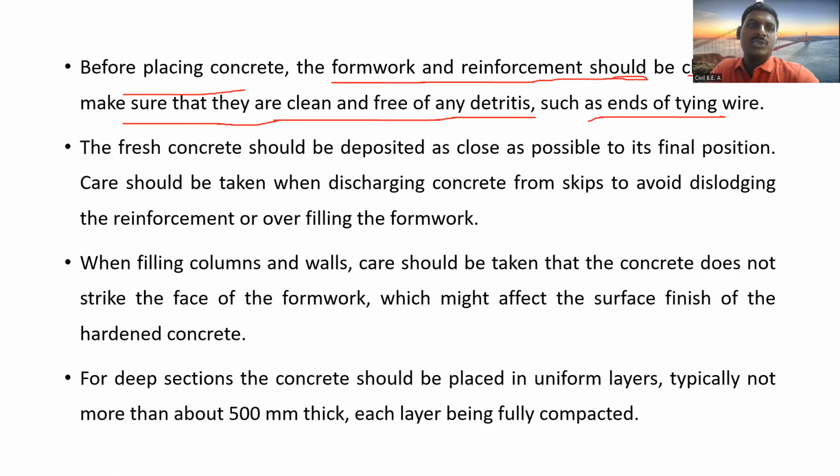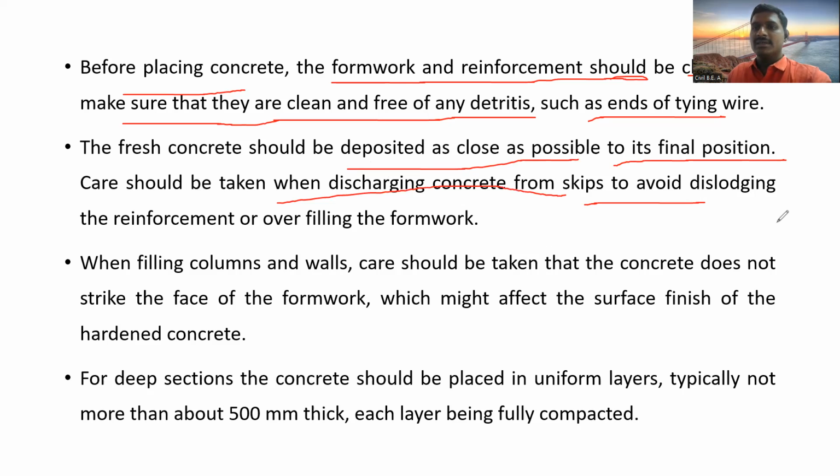So before placing the concrete, we have to check the formwork and the reinforcement, and make sure they are clean and free from any disturbance. Then the fresh concrete should be deposited as close as possible to its final position. Care should be taken when discharging concrete from the skip, to avoid dislodging the reinforcement or overfilling the formwork. That we have to take care of.